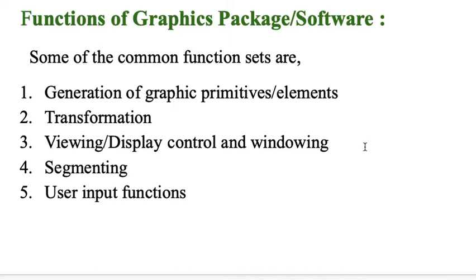If the object is too complex to show in its entirety, windowing is often used. An imaginary box is created around the portion of the object of the user's interest. Windowing results in displaying the portion of the object encompassed by the imaginary box.